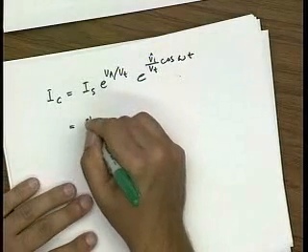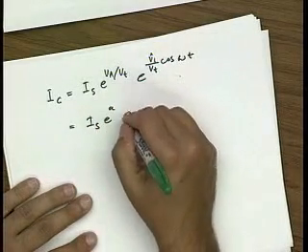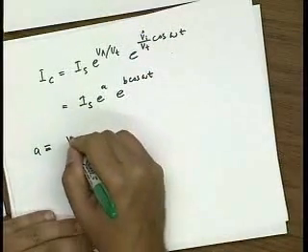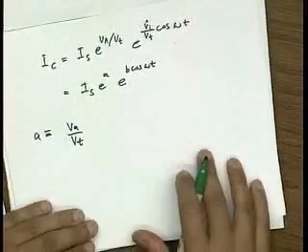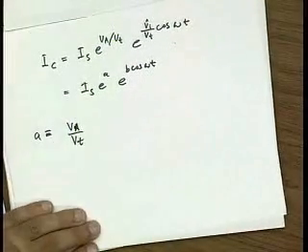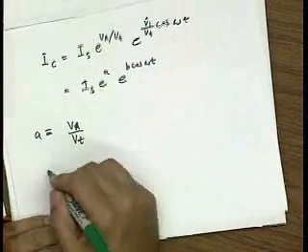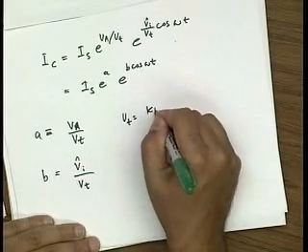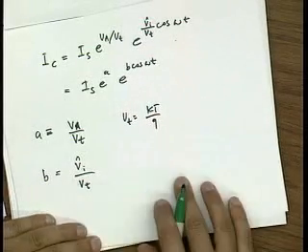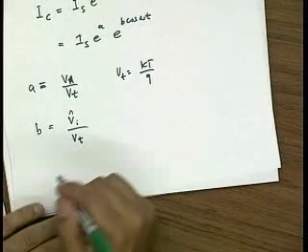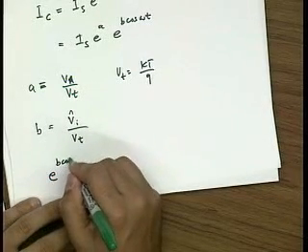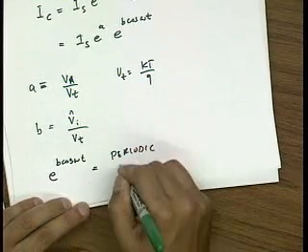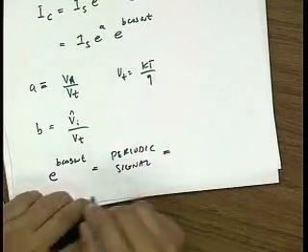And we can write this in normalized form, e to the a, e to the b cosine omega t, where a is basically the bias voltage, VA divided by Vt, and b is the normalized input signal. Okay, and the important observation, if I look at this signal, it's a periodic signal, and so I can do Fourier analysis on it.